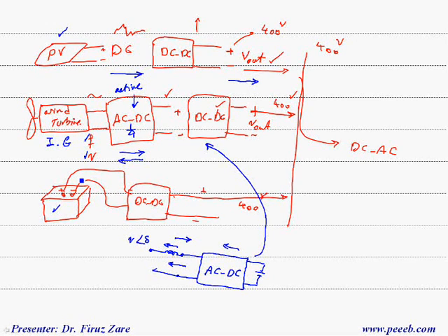We have to transfer the power into the DC line, but the point is that when we have significant power coming from PV and wind turbine, then we should be able to charge the battery. So that's why it's quite important to design a power converter here, DC-DC, which should be bidirectional. That means charging, this is the power flow, discharging, this is the power flow.